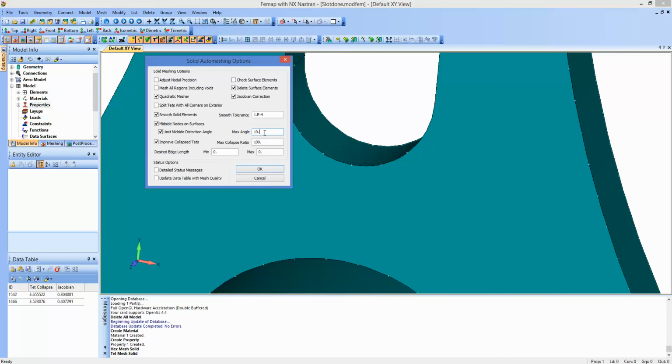So that was kind of a wordy explanation. Does that make sense? That explanation does make sense, and the mid-side node on the geometry is very useful for us when we're doing our crack meshing in FEA crack. That mid-side node really helps the brick elements follow the curvature when we're doing a crack mesh transformation. So this is really helpful. Right, I highly agree.